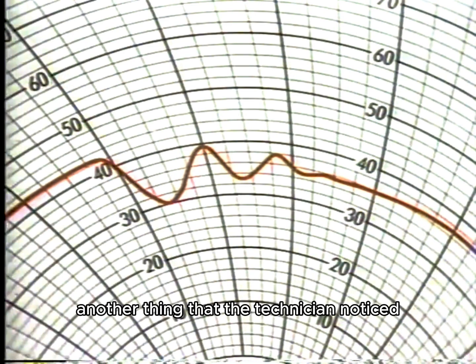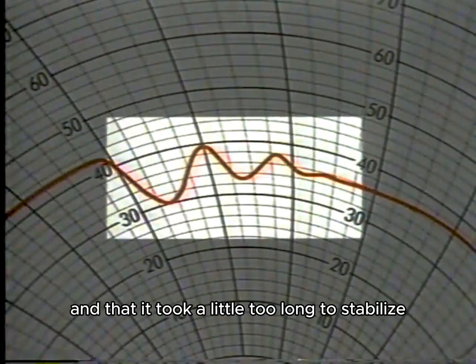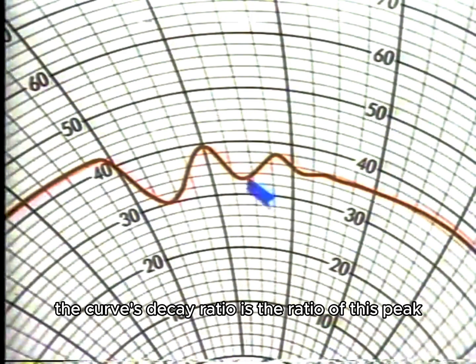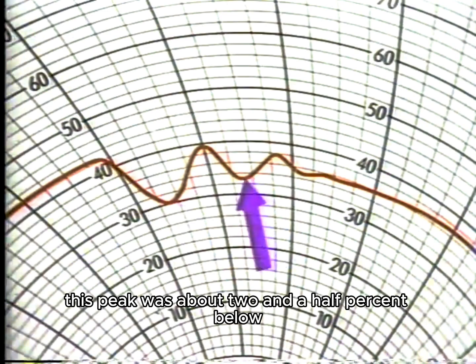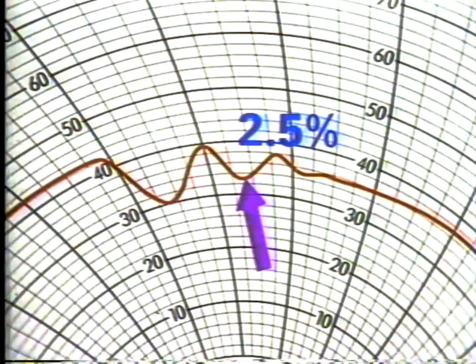Another thing that the technician noticed was that there appeared to be excessive cycling and that it took a little too long to stabilize. The curve's decay ratio is the ratio of this peak to this peak. This peak was about 2.5% below the point where the cycling stopped, 36%.